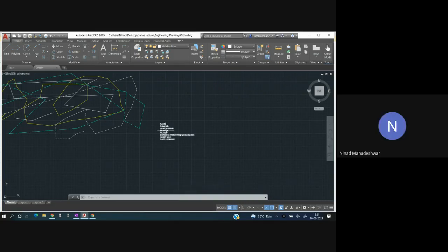And this nameplate should not be in hidden lines. It should always be in zero lines, that is the drawing line. So the layer should be drawing line. This can be done in any other line also, center line also. If it is center line, this entire part will be blue. If we do this in projection line, it will be yellow. So you get the point. This entire part should be in drawing line. Getting this, everyone?